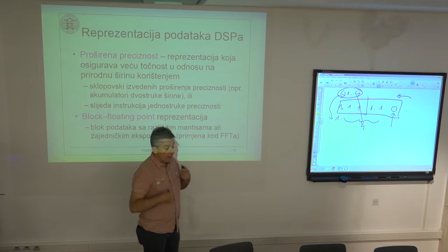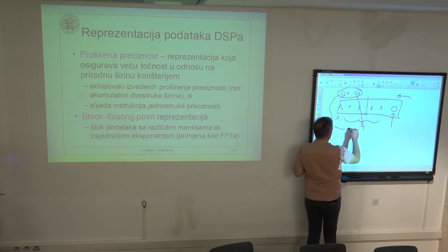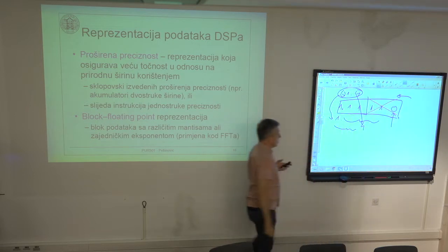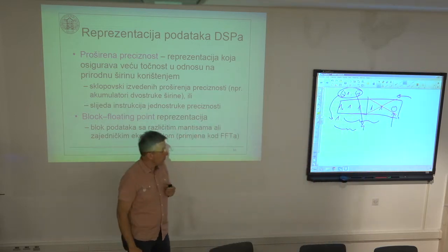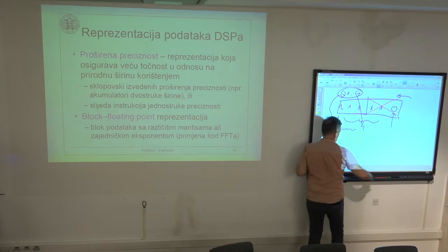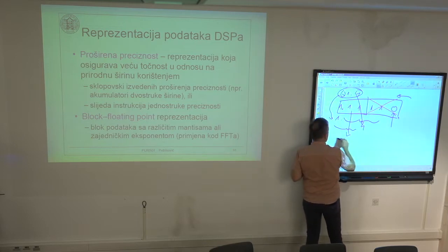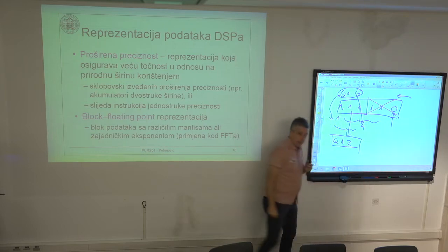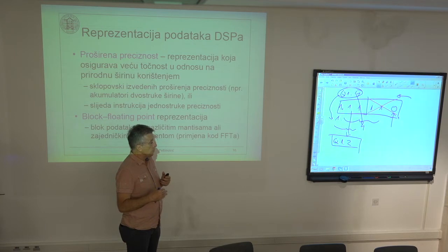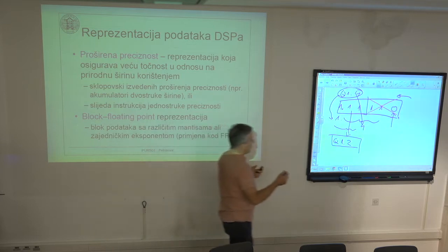Okay, and if I want to do the quantization to the single word precision, I simply take the upper word and reject or truncate or simply remove the lower word. I reject this lower word. And I get the result. So the result is simply the upper word. And this truncation would produce Q1.2, this upper word, and the error would be always negative. The actual value after truncation is always negative. It is less than the real value, less than the proper full value.